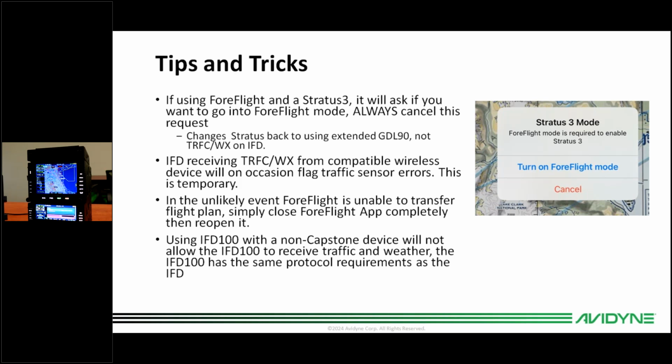And if you're using the IFD100, our app, with a non-Capstone capable device like a Sentry or Stratus or Stratus 2S, you will not get traffic and weather on the IFD100. The reason for that is it has the same protocol requirements as the actual IFD in your aircraft.